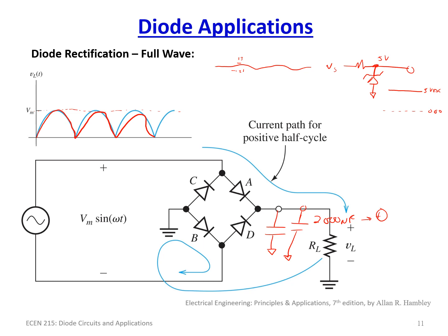So you could have this ripply, nasty signal coming in, but because of this resistor R and this Zener diode, you'll get a nice, clean looking signal. You can actually use this right now to power various equipment. It's very inefficient and it's not used normally today. There's a lot of DC to DC converters and AC to DC converter circuits that are switching regulated to have basically transistors driving things. But this technique is still valid and is still being used today.